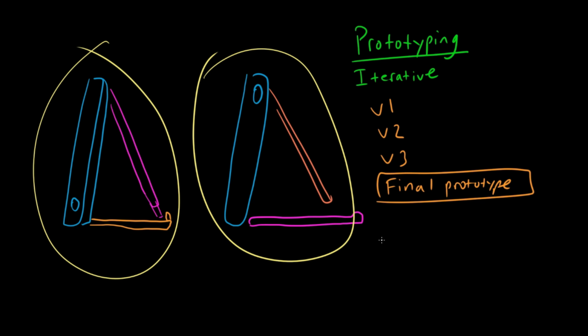And to do this, we're gonna need to keep in mind tolerance, which is how well something fits into another piece. We're gonna have to keep in mind correct measurements. And during the slicing phase in Creality Slicer, we're gonna have to keep in mind how much infill we're gonna have for the strength and durability of the product. All right guys, so now let's head over to those calipers and the screen and get those measurements.